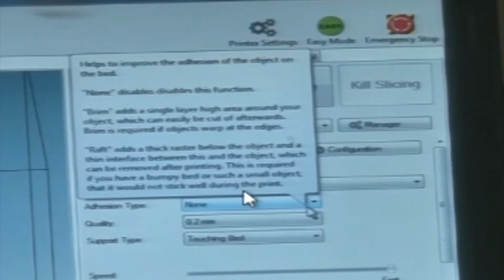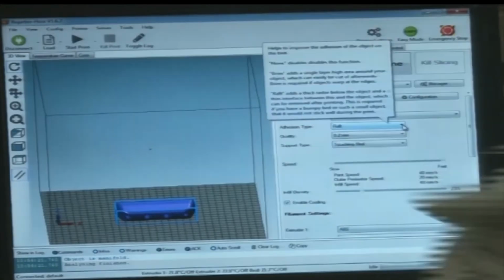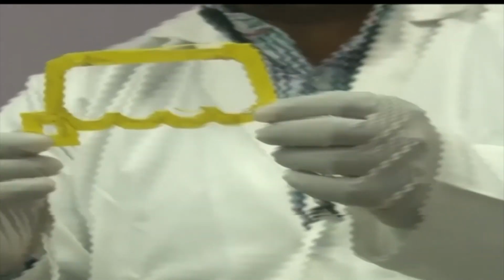So I think this makes it very clear. Normally we don't use this feature, brim or raft; we have just kept it in here. We can use this feature only when we find that our job, whatever we are going to print, is perfectly flat at one end, that is rectangular, cuboidal, cubical, at the cross section or at the bottom of the job. Then we can use this. We are going to demonstrate this, but we are going to clarify that this one thing, this is brim.